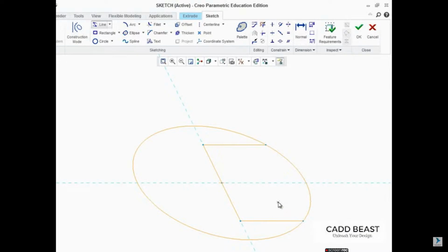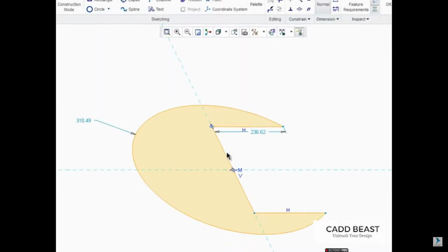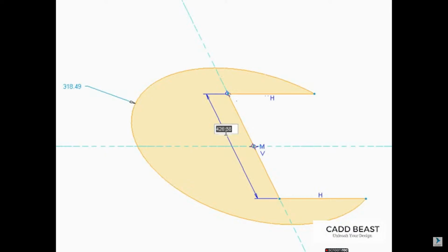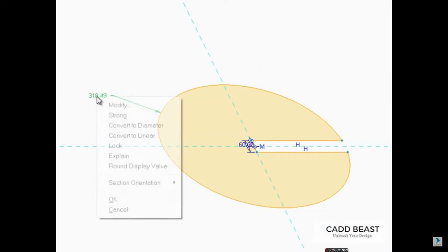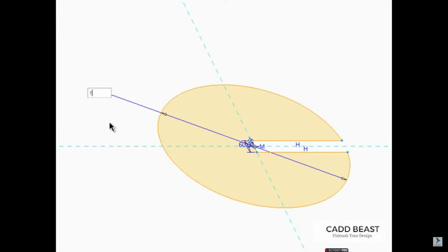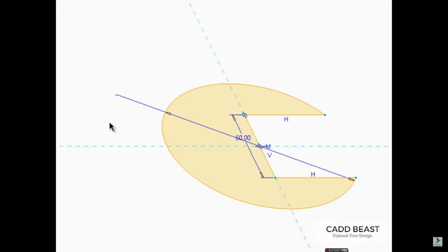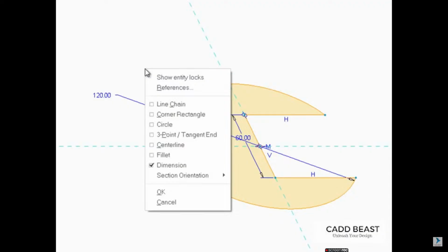After two pieces of the circle are trimmed away to create a closed loop, you'll notice that Creo Parametric controlling the dimensions of a sketch is simple. Let's make the gap here 60 and the size of the arc controlled by a diameter dimension of 120. Once the sketch is complete, close the Sketch tab by right-clicking and selecting OK in the pop-up menu or by clicking OK in the dashboard.